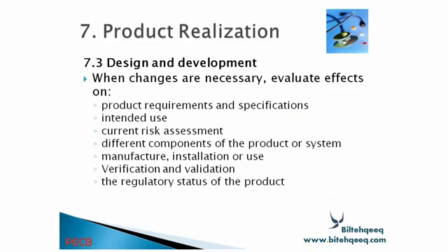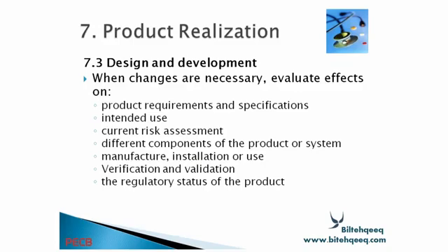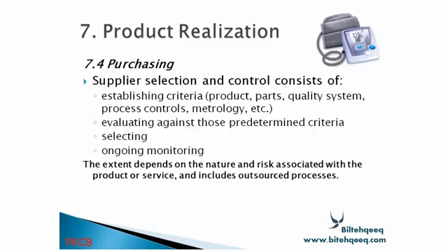You also have to study the effect of the change. If you change the design, you have to evaluate what effect it will have on product requirements and specification, intended use, current risk assessment, different components of the product or system, manufacture, installation or use, verification and validation, and the regulatory status of the product. So if you are going to change the design, you have to see each and everything very thoroughly, what impact it has on the other activities.